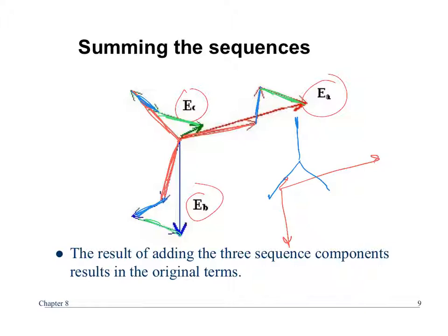No way, Jose. If I monitor the 3 lines and I put a donut CT around all of them, that's going to calculate the 3 magnetic fields going through there, right? And the sum of those, if they're perfectly balanced at 120 degrees, should be 0. If they are not, then they are not. So back in the day, to monitor zero sequence current when you didn't have a ground available, you actually just put a big window CT around all 3 phases, and that's how you measured ground current.